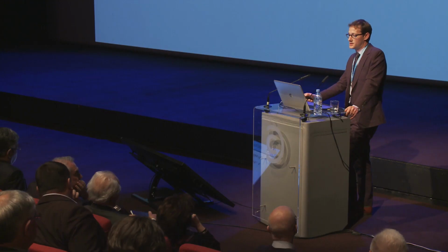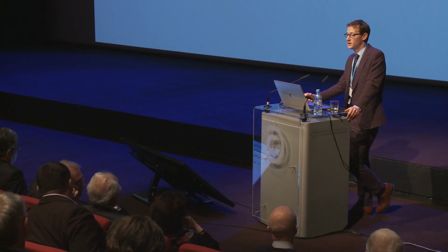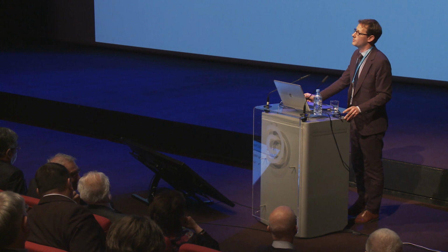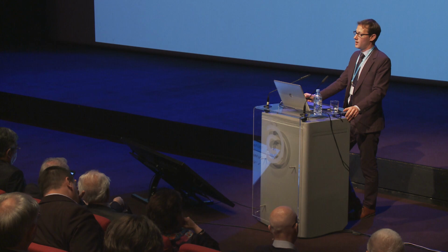So the BIM Basics. What we needed to do is have a defined end game for all our data. So this starts right at the beginning about what type of data you're going to collect, how you're going to collect it, all the individual attributes associated with that data. You need to know how to classify your assets and data structure. And this is all procurement critical. So right at the beginning, we wrote into contracts with our supply chain exactly the type of data that we needed from them. We prescribed where they were going to put it, how they were going to put it there, so that everyone could rely on that.